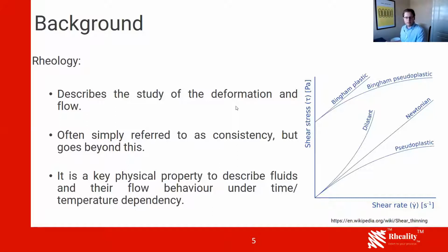It is a key physical property to describe fluids and their flow behavior under time and temperature dependency. And that is another thing where it will be very important to have rheology, unlike a viscometer measurement or consistency meter measurement, because these measurements are affected by time and temperature. Rheology takes those factors into account.